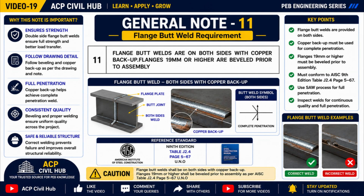General note number 11 explains the welding requirement for flange butt joints in built-up steel members. According to this note, flange butt weld shall be provided on both sides using a copper backup. In addition, all flange plates having a thickness of 19 mm or more shall be beveled before assembly.